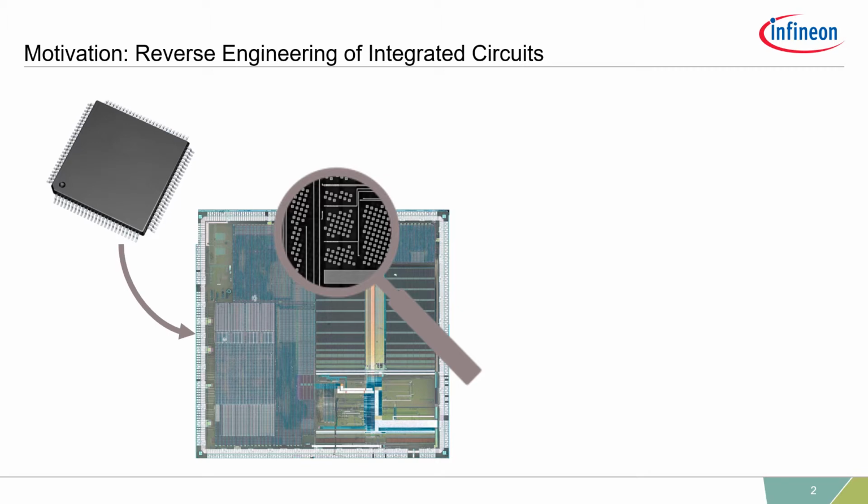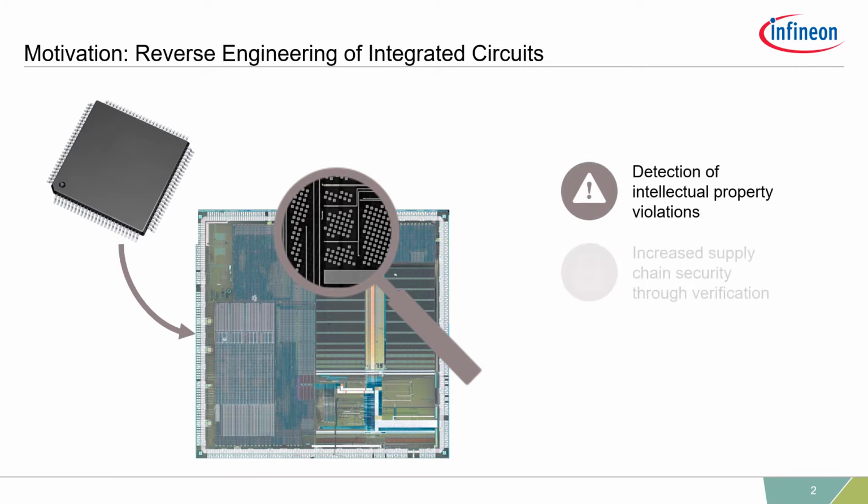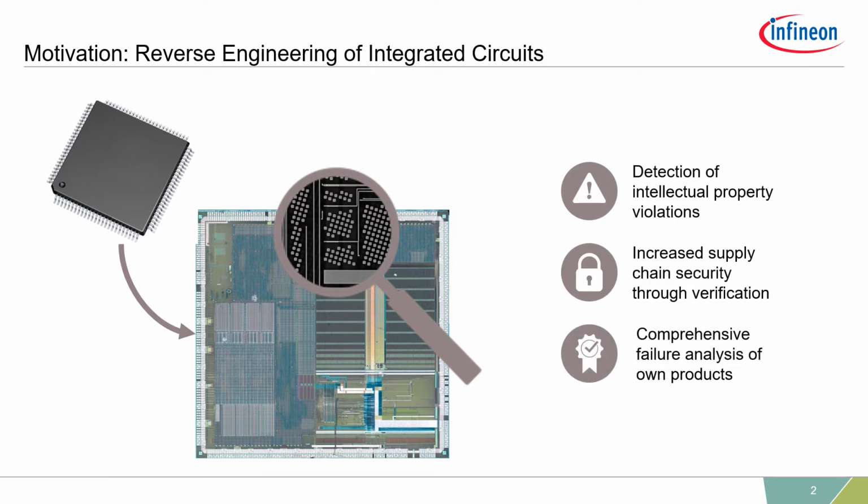Circuit extraction is a complex chip-destructive procedure to gain knowledge about the microcontroller functionality. For this purpose, a few nanometer-sized structures can be extracted and analyzed. Of course, such a time-consuming and costly procedure is only used for certain questions that cannot be sufficiently answered by less invasive methods. Typical objectives include detecting intellectual property infringements as well as investigating the product integrity.